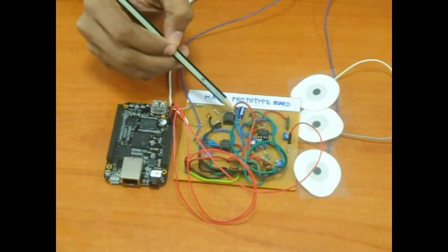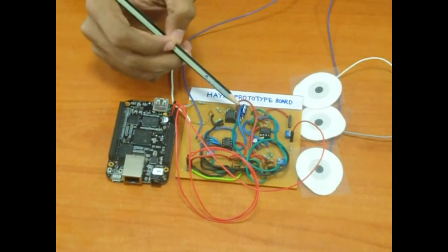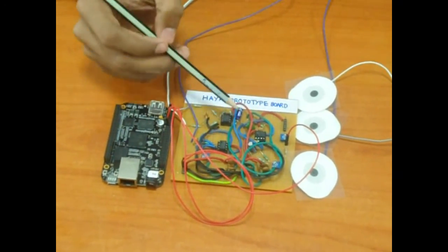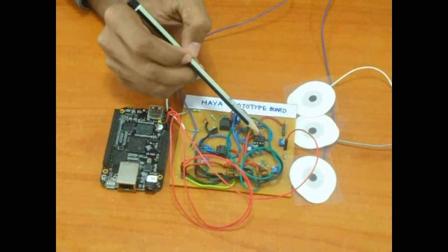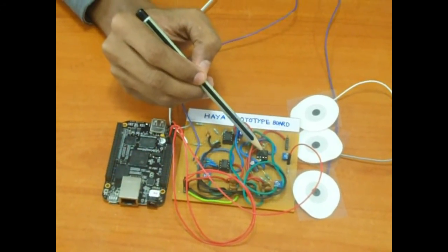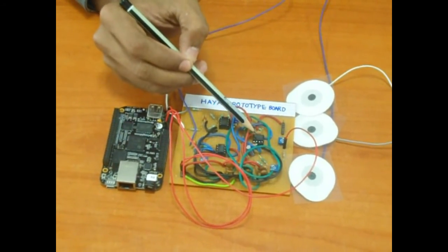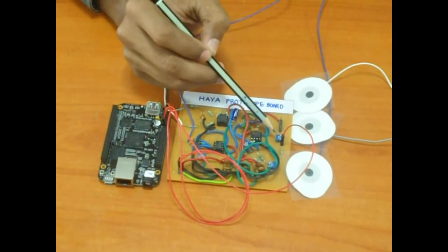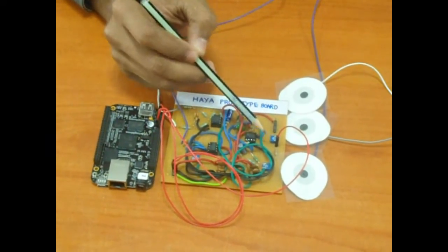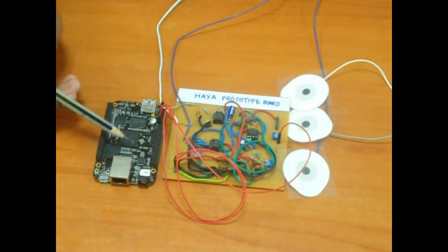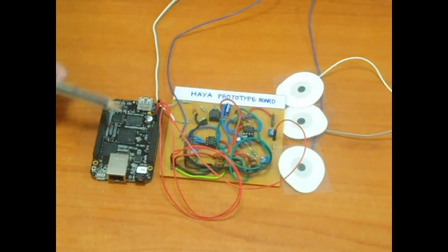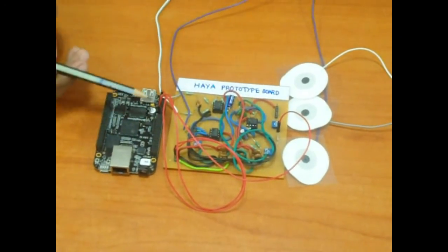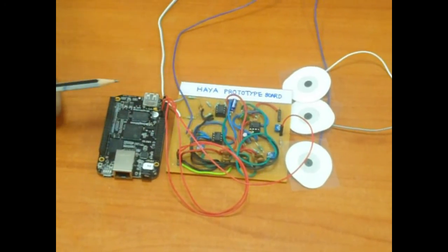The output of instrumentation amplifier is connected to a high pass filter whose cutoff frequency is set as 0.4 Hz, and then to a non-inverting amplifier, and then output of non-inverting amplifier is connected to a third order Bessel filter. Then the output is given to a potential divider circuit, which controls our output in a range of 1.8 volt, and it's connected to the BeagleBone Black, where all the software process is happening, and it is connected to the analog to digital converter pin 40, and we have given the voltage as well as the ground.